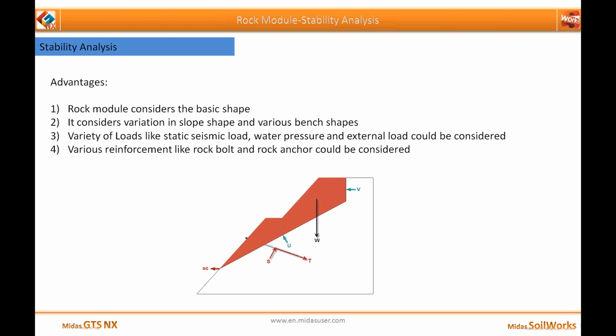Now the advantages of the rock module are that it considers the basic steps. It considers the variation in slope shape and various bench shapes, and a variety of loads like static load, seismic load, water pressure, and external load could also be considered and their influence studied. Various reinforcements like rock bolts and rock anchors could also be considered to check the stability of the rock.